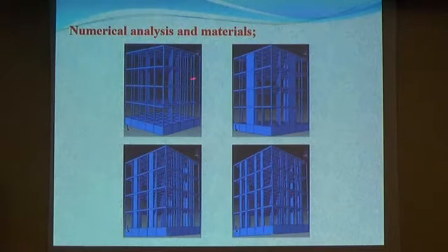We use 3 types of shear wall. In the first, the shear wall is installed at the center. In the second, the shear wall becomes half and is located at the second span. In the last, the shear wall is divided into 4 parts, and we install them at these 4 points.